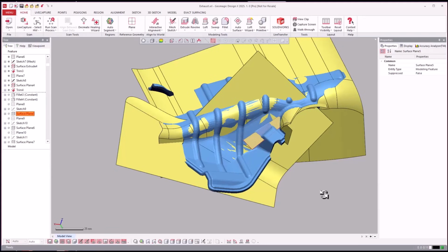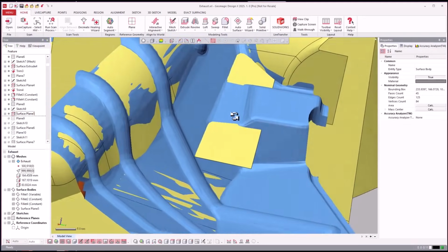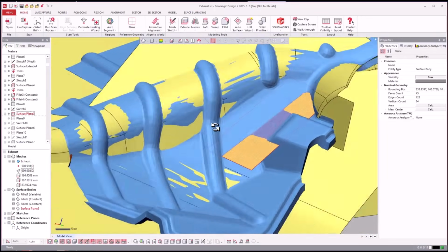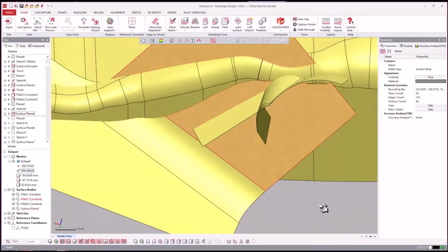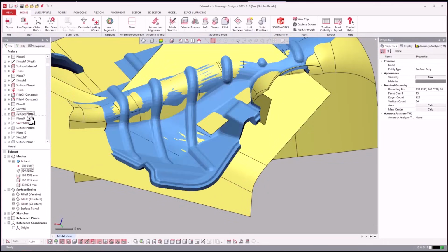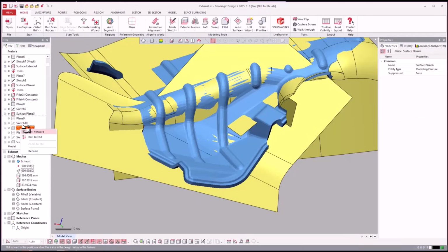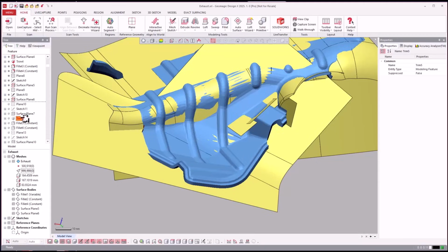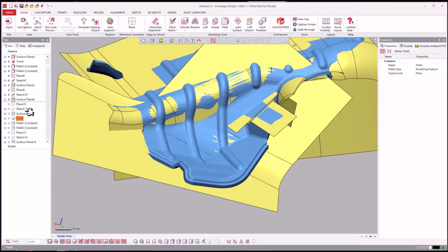So this is another one of these fit. We're going to fit here, fit there, trim these tools together. And just turn that off and turn that on. You see we had this piece there. Just break it down into smaller pieces, right? And just nibble away at it by fitting the individual sections and trim them all together and fillet them where possible, as you can see here.